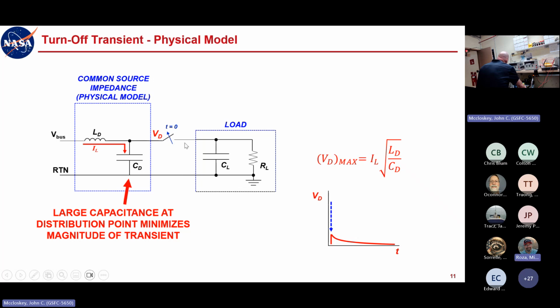That's Mike, right? Yep. So what Mike is saying is, well, what if you've got a fuse, and what if you've got a short in the load that pops the fuse? Well, it's basically the same. It will have the same effect. Obviously, the cause is different, between an intentional command to open a switch versus popping a fuse. What I haven't really shown here is there's generally a fuse in series with the switch. But you pop the switch, well, you've got something that open circuits your load very quickly, and so it'll basically be the same type of thing.